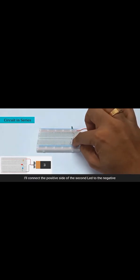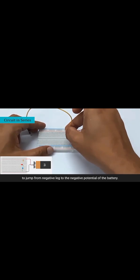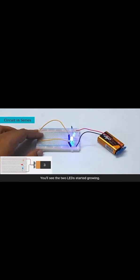I'll connect the positive side of the second LED to the negative side of the first LED as we are connecting it in series. Now to close the circuit, again I will use a jumper cable and I will jump from the negative leg to the negative potential of the battery. You'll see the two LEDs started glowing. It means this kind of circuit is called a series circuit.